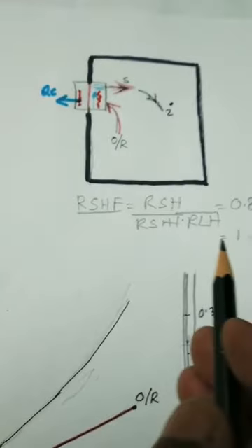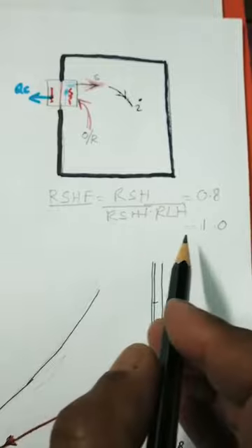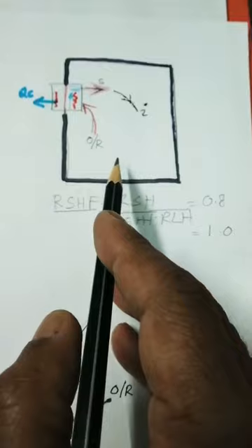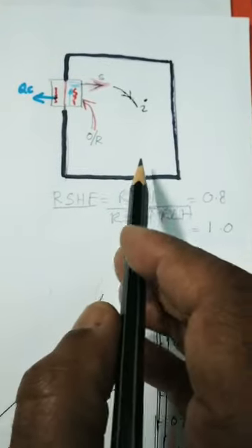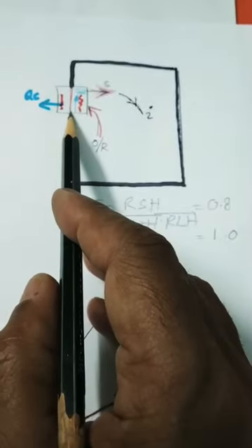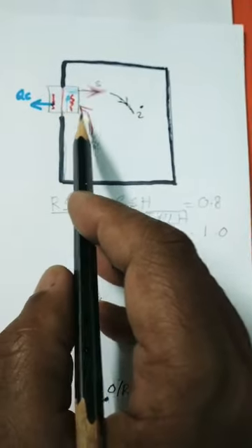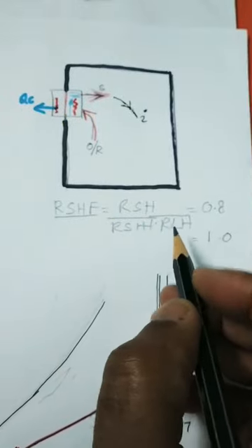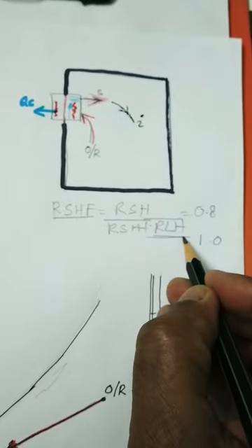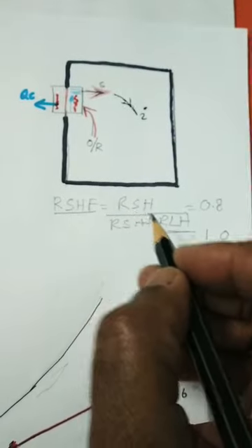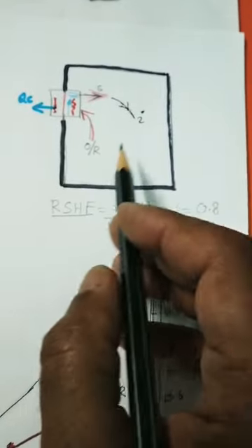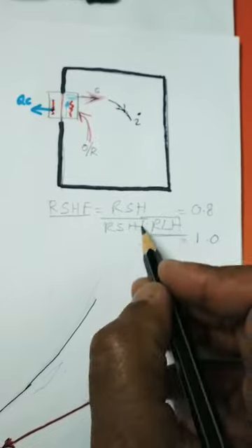So what does that mean? It means that the room sensible heat factor will become 1 if there is no latent heat load. This room will not produce any amount of humidity in this area, and therefore the air will not have any problem of latent heat or any humidity which has gone up or gone down. So there is no humidity factor here, if room latent heat becomes 0,